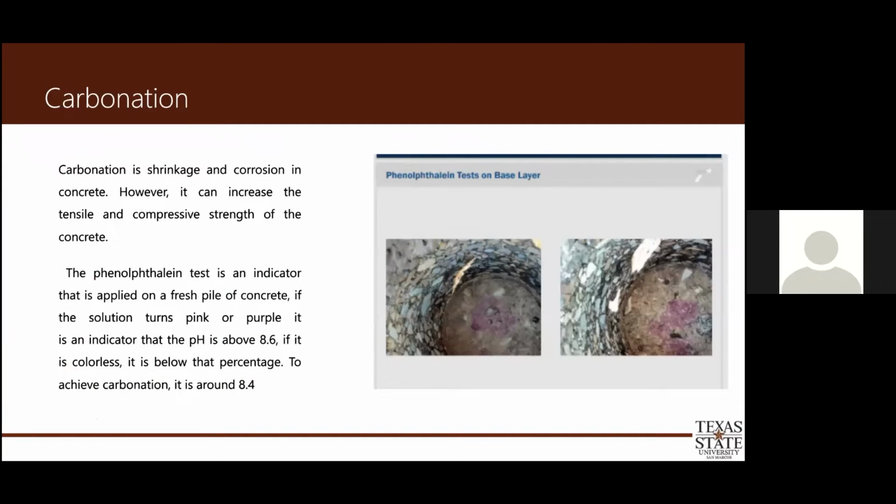Cement, the concrete's binding agent, has a pH level of 11, making it alkaline. For cement to effectively hold the various components in it, it should have a pH of around 11. The problem is that Portland cement does not resist many acidic compounds very well. As the pH decreases below 6.5, concrete deterioration increases, and the more the concrete deteriorates, the more porous it becomes.